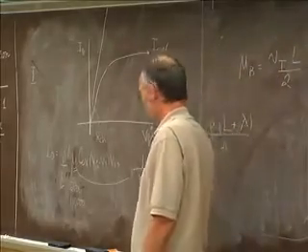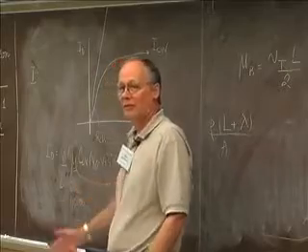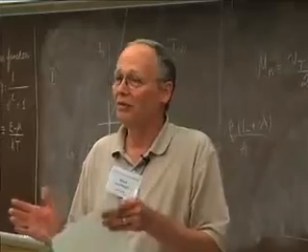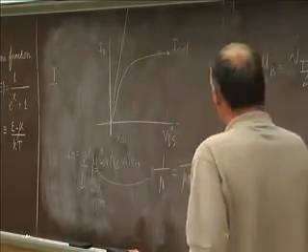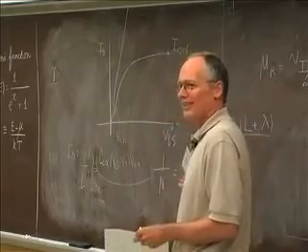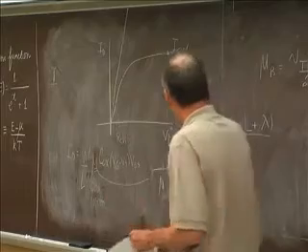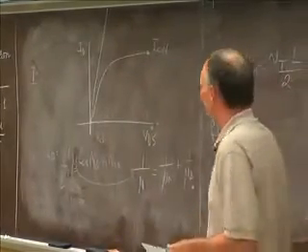Now we're limited more by the actual mobility, and that's so much higher in 3-5s or graphene that in a longer channel length device you could still get very good RF performance or high-speed performance. So if you're looking for RF performance, that's an advantage. If you're looking for density in a digital circuit, you're going to make these transistors as small as you possibly can. And then this ballistic mobility is going to limit you.